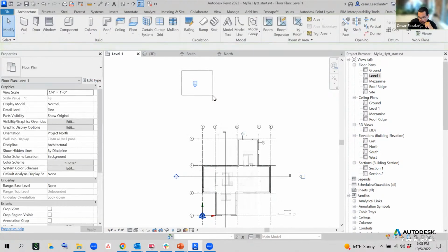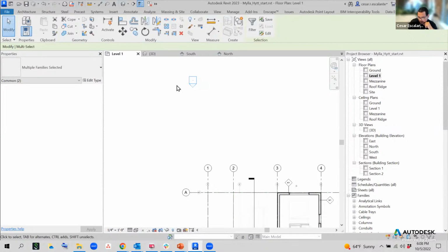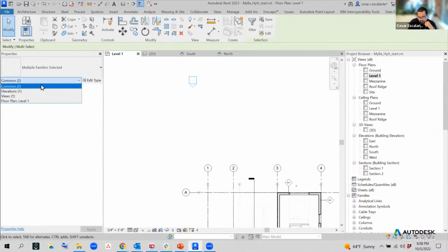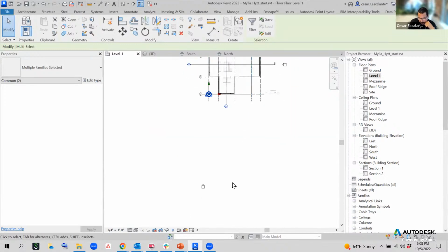Same here, select two elevations. I do a window selection to select two objects. Notice that one is the elevation marker and the other is the elevation view. And you just drag it, relocate it to where it's closer to the geometry. And I think that's what's happening here. When you select the elevation marker,